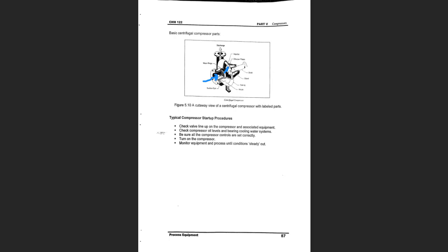And as the gas leaves the casing through the volute, guys, what happens is that it will decelerate, the speed will decrease, and that causes the pressure inside the casing to increase. And then after that, the gas will flow through the discharge side of the pump.